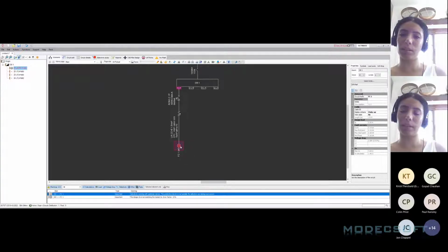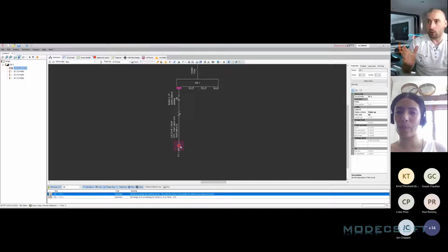Right, so we put all the manufacturer data or the manufacturer specific curve data within the software. So where we have different makes and manufacturers, we will refer to their curve data in their catalogs or the information that they provide us for their protected devices. And things like maximum Zs values and these sorts of things, this data is then extrapolated from those curves.